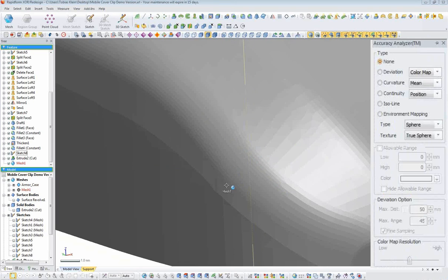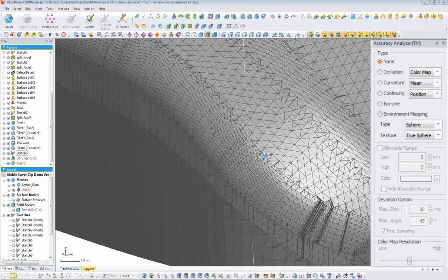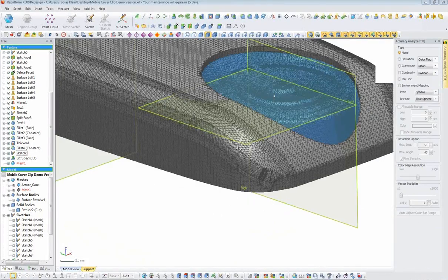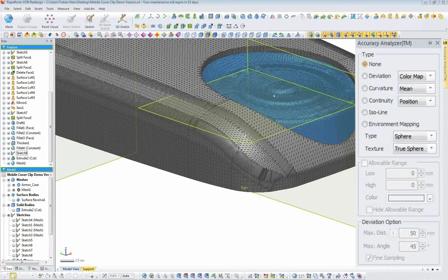the radius is segmented into several lines of triangles like this, and this is based on the curvature. So the higher the curvature, the more triangles are generated normally, and the lower the curvature, the fewer triangles are generated. So you minimize the deviation from the original CAD model, and if you want an equally distributed chord length, then you can also define the chord length manually. Okay, any more questions?